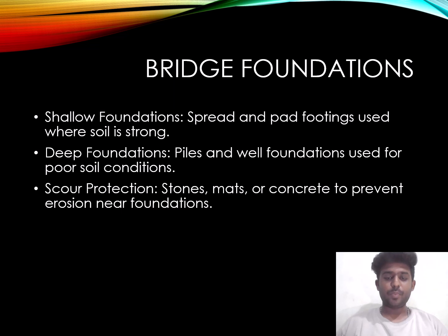The next topic is bridge foundations. First, shallow foundation, spread and pad footing, used where soil is strong. Deep foundation, piles and well foundation, used for poor soil conditions. Scour protection, stones, mats, or concrete to prevent erosion near foundations.